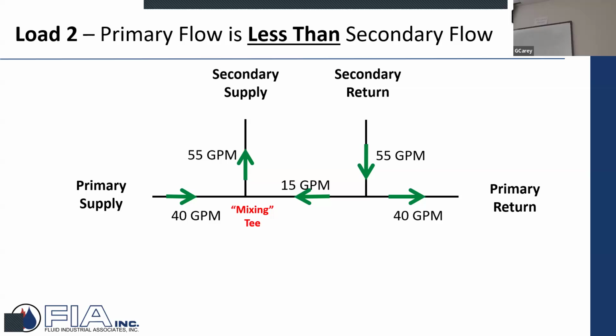So then you get into this thing here, a mixing T and a diverting T. So I'm taking 15 from the return and I'm mixing it with 40 from the hot, call it hot, whatever, it's chilled water or hot water, but I'm mixing, so I have a mixed supply going to this 55. And then from a diverting, what happens is mixing is 2 ins, 1 out.